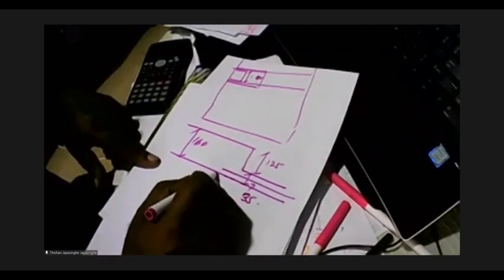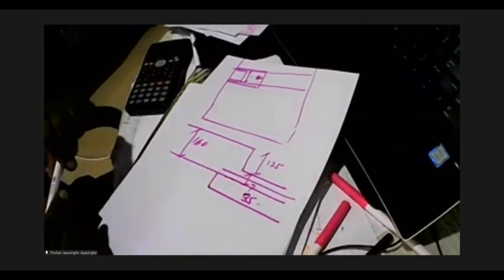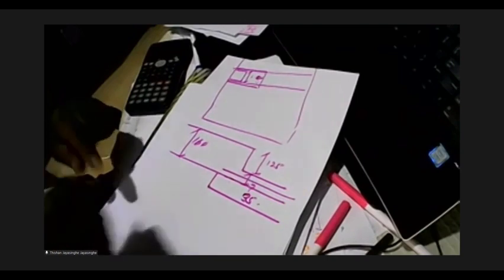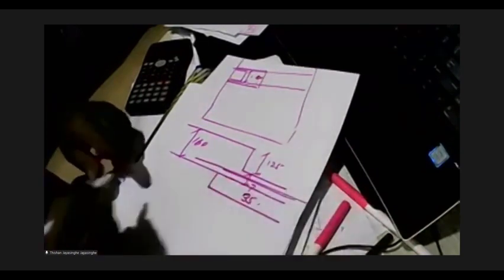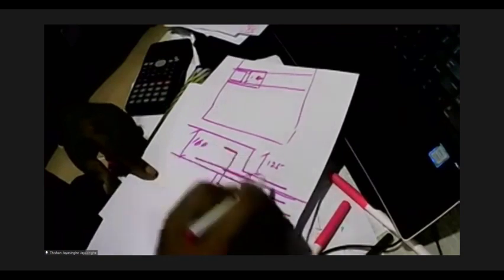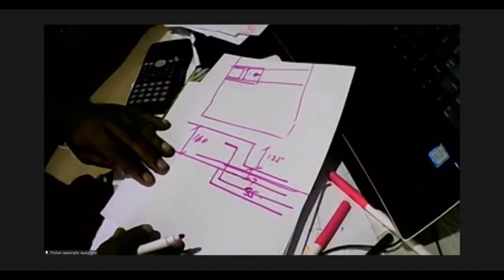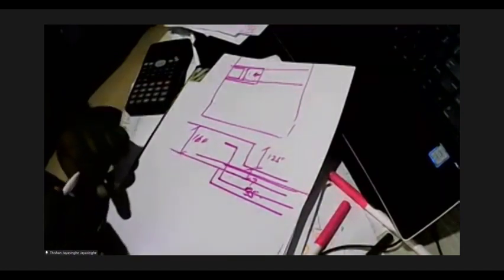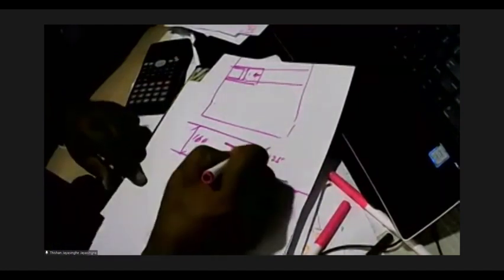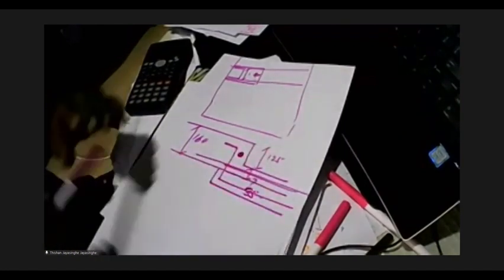So you might have to drop the slab like that. But it's okay to do that with some reinforcement here, and then you'll have some reinforcement to ensure that the slab is properly hung. And then the pre-stressing tendons will run on the side of the opening.